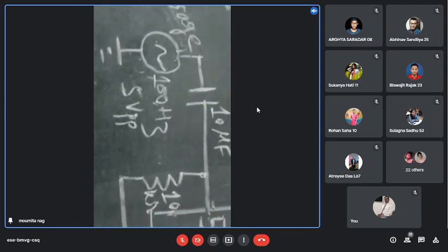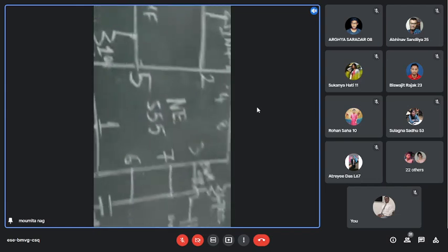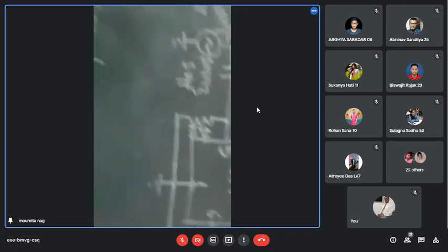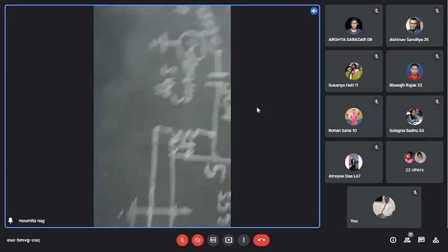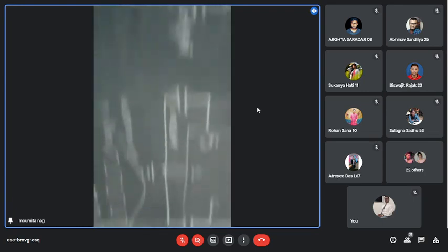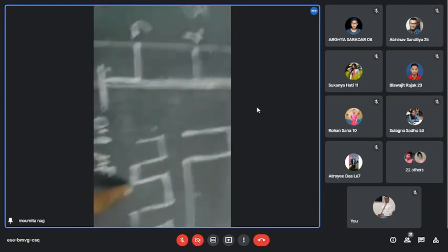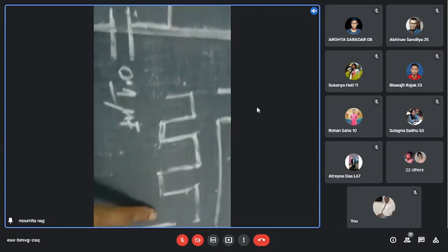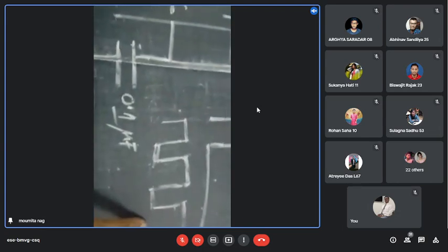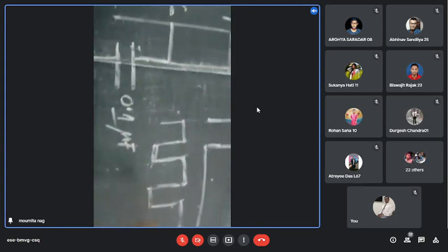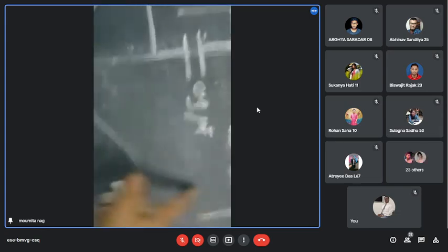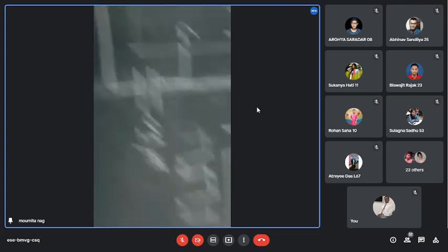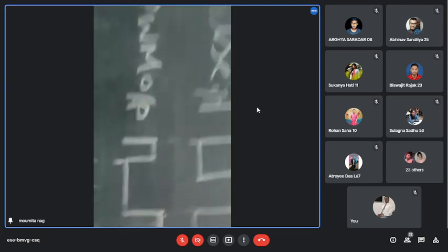So at the output, that is at pin number 3, in the absence of the message signal, this type of pulse will be generated, and when I give the control signal, that is the message signal at pin number 5 of the first timer, then the PWM signal will be generated like that.